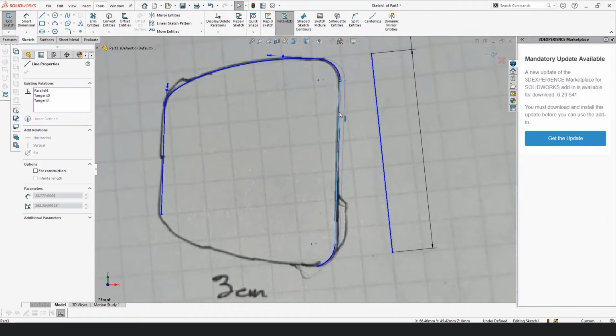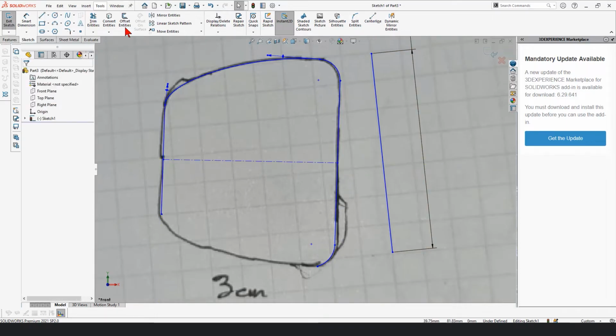Or do I? Because we have to talk about something very important, or else everything else we do from this point onward is gonna be a moot point. The sketch is more or less as big as the light. We just drew it on a piece of paper and we scaled it right. But what if our manufacturing process's tolerance creates this pocket slightly smaller and our light won't fit into this pocket? If it happens, then it doesn't matter if the rest of the components line up and assemble together. The light, which is the final purpose of this design, wouldn't fit.